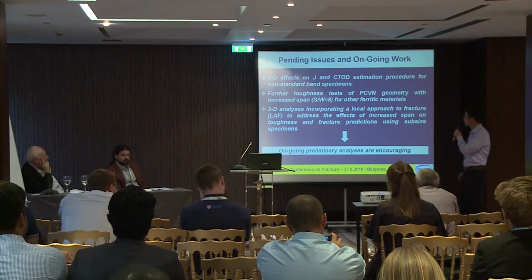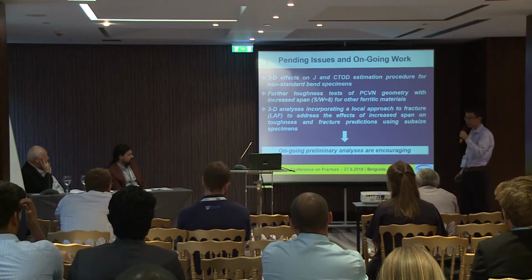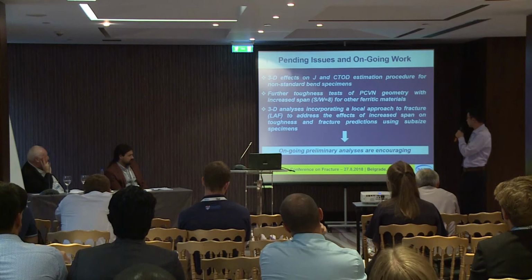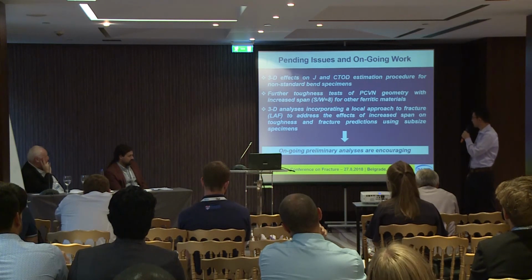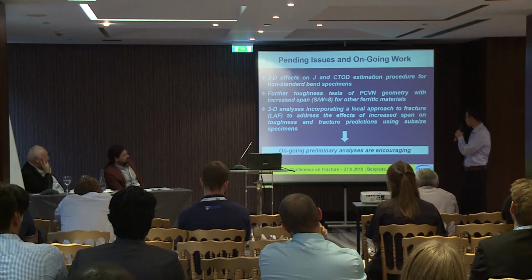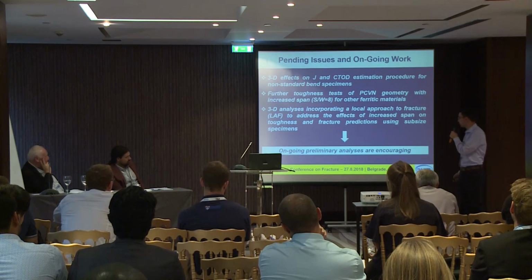further toughness tests of pre-cracked Charpy geometry with increased span for other ferritic materials, and 3D analysis incorporating a local approach to fracture to address the effects of increased span on toughness and fracture predictions using subsized specimens. And the ongoing preliminary analyses are encouraging. That's all.